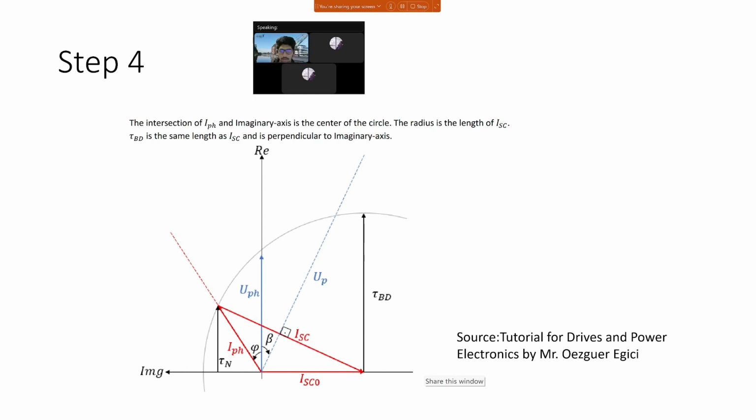And we know the nominal torque because we know the nominal power. So using the first law of drives, you can get nominal torque, and then if you measure this length and measure that length, do a ratio, you can get the breakdown torque.